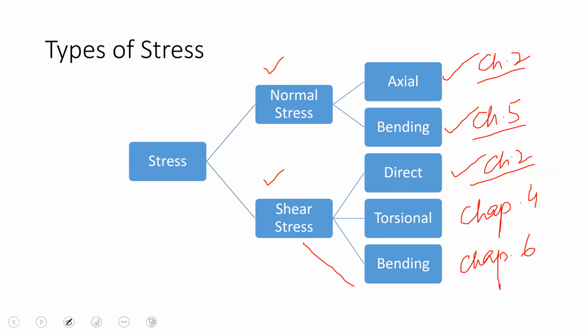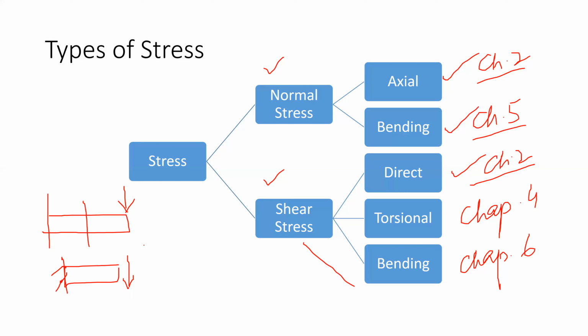This means the shear force that is purely generated in the component because of the transverse load being applied, right? So whenever there is some bending, there will definitely be a shear stress. This is what we have already seen: if we have a beam like this and apply a transverse load, again chapter 5 and 4 as well, and we take a section over here and draw the free body diagram from here to here, we will see that there is always a positive convention for the bending as well as for the shear.